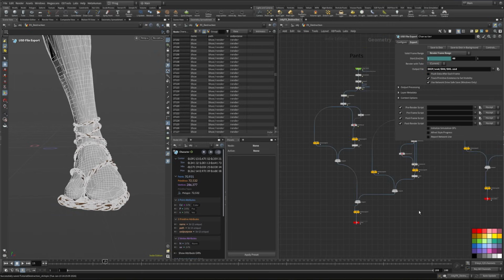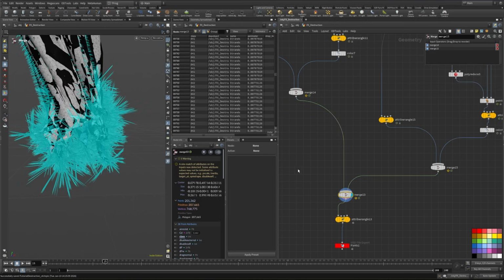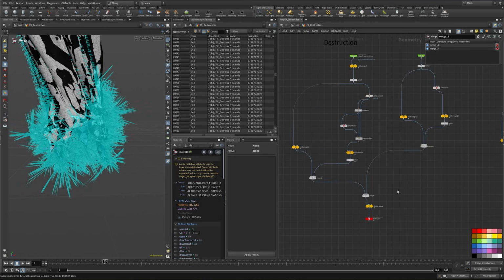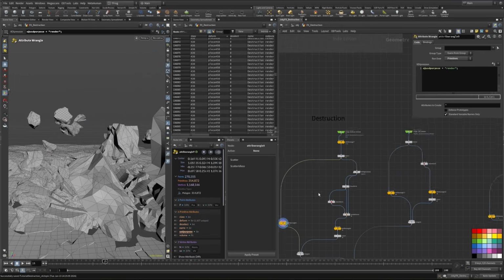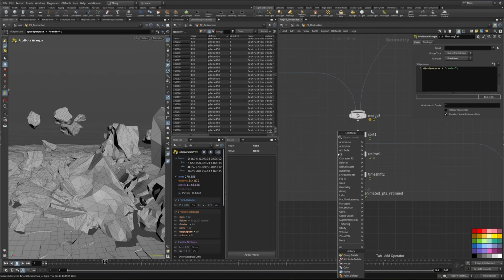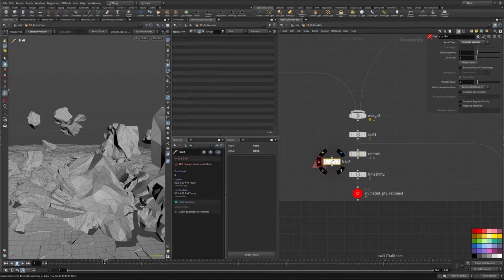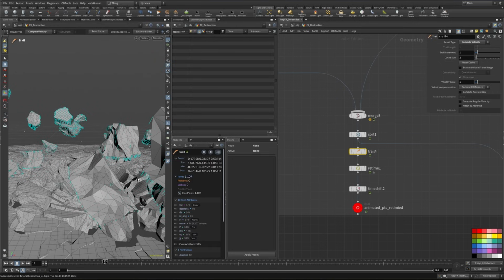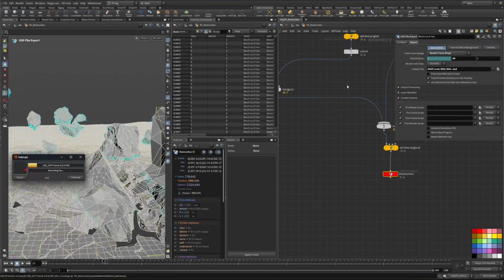Now let's watch if everywhere is my velocity as well. So inside my pants, we definitely have our velocity here, as you can see. For the destruction, let's watch it in the render. I think there is some missing, so we can again plug it in before the retime. So let's add a trail node over here using compute velocity, plug this inside. And now we got our velocity here. Great. And we need to hit save to disk again, like so.